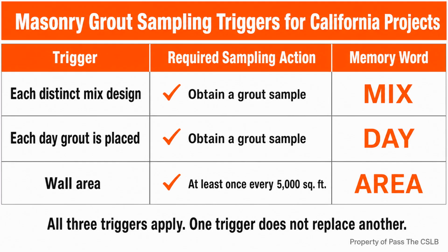Reinforcing steel introduces a safety boundary that has nothing to do with whether a cap is brightly colored. The question is whether the protection is designed and tested to resist impalement. The research states that exposed protruding reinforcing steel up to 6 feet above grade must be covered. For protection from falls up to 7.5 feet, the cover must meet specific size and performance requirements.